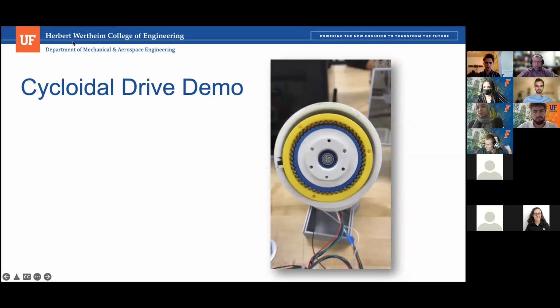And the cycloidal pins were one of the things we would change if we had to do this design again, because we worked on trying to drop it to 11 pins during the semester, switching out the cycloidal drive and having a much smaller gear ratio, but also not taking as much time and components to complete. What we found was it would start to slip at those smaller amounts of pins. So if we were to improve on this concept, we would probably try to find a happy medium between the two.